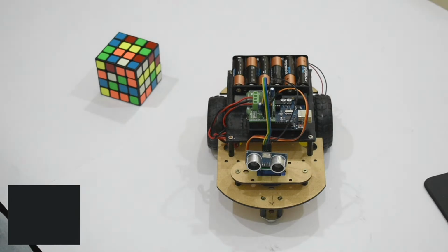Before we go inside the loop function, this is very simple. As we did in our previous session, we had defined functions for how our car is going to move forward. For it to move forward, we had defined a void forward, and inside this we said that the Arduino is going to supply high voltage to the red wires of my left and right motors, and low voltage to the black wires of both the left and right motors. That way my car is going to move forward.